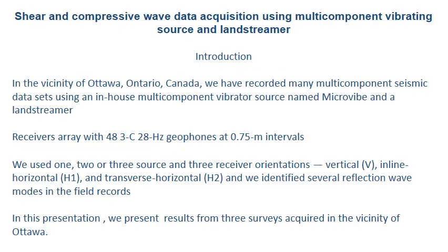In the vicinity of Ottawa, Ontario, Canada, we have recorded many multi-component seismic datasets using an in-house multi-component vibrator source named microvibe and the land streamer. The receiver array has 48 three-component 28 Hz geophones at 0.75 meter interval.